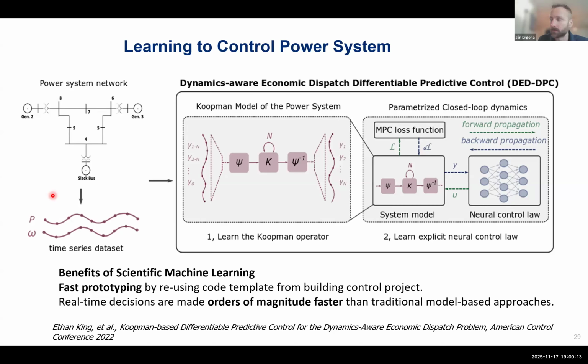So this is, again, a hard optimal control problem that requires solving the physics, which is, again, given by differential algebraic equations. So in this case, we approximated with a deep Koopman model, and so this is offline, by training these approximate control policies. And when compared to full nonlinear model predictive control with differential algebraic equation solvers, we get 5 orders of magnitude acceleration at inference time.